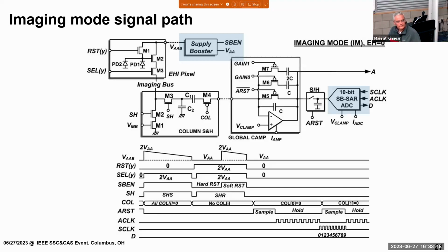Do you have a number for the dark current that you got? Yes, in the paper I have. Okay, per area, okay. Yeah, I have everything. That's why we always do full disclosure. How does the dark current compare to the regular CIS? Well, regular CIS, they have certain ways to solve that problem. They don't really report the real uncorrected process leakage. And for CIS processes, they have this STI retreat that they use to avoid that dark current and leakage. So in FOX, you don't really care about that.